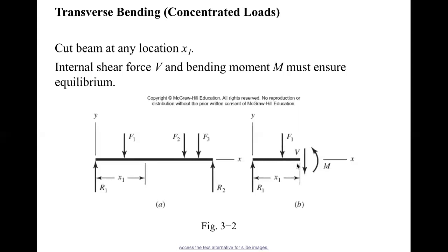And there are two reactions at the cut. One is the shear, V. The other one is a moment, right? So shear, we call it a transverse shear. And moment, we call it reaction bending moment. There's no other type. I only have the V and the M.